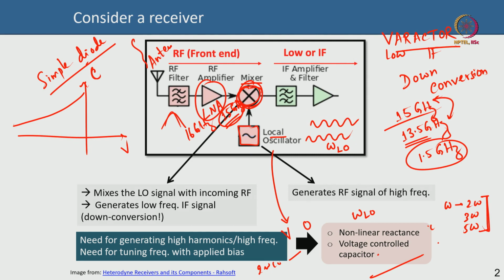Okay. So, a simple diode can actually behave as a varactor or as a frequency multiplier, but it is not that simple in real application. You have many more advanced versions: anti-parallel diode, double down conversion diode, and then different kinds of frequency multipliers, planar Schottky multipliers, and many complicated circuits in terms of local oscillators and mixers. You can implement them in chips, and so the varactor or the frequency multiplier will be a component of that entire chip, for instance. Okay. And what is the difference between a varactor and a frequency multiplier? A frequency multiplier is a type of varactor.